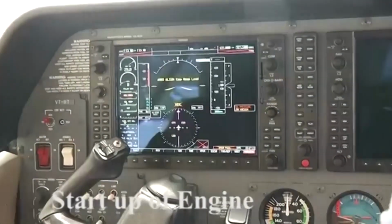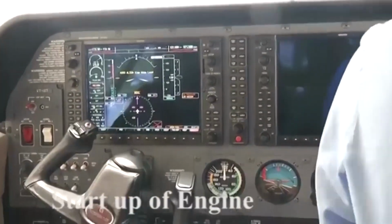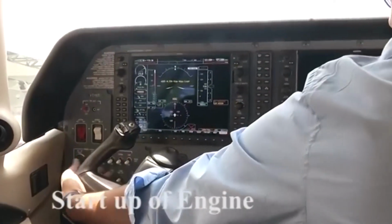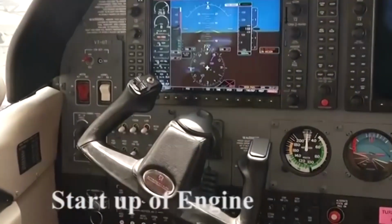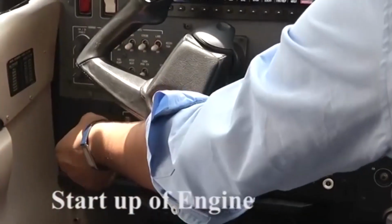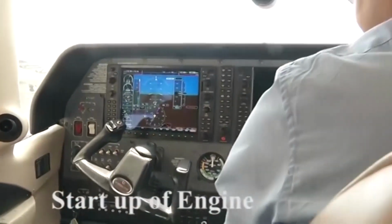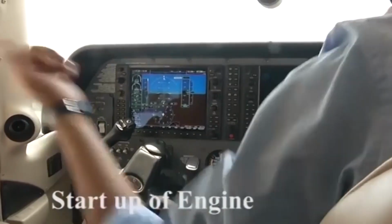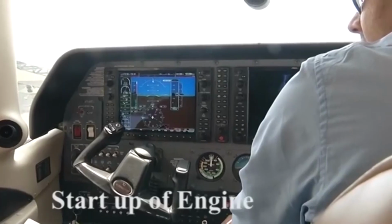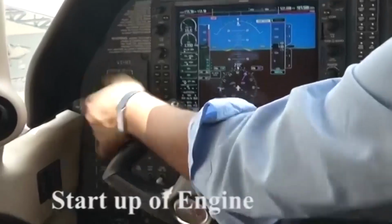Now mixture in, throttle half inch in, fuel pump on, then fuel pump off, mixture out. Then crank ignition, right, left, both, then start. Now engine start. Now alternator on, avionics, beacon, nav, stop.